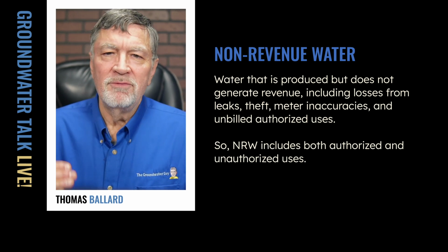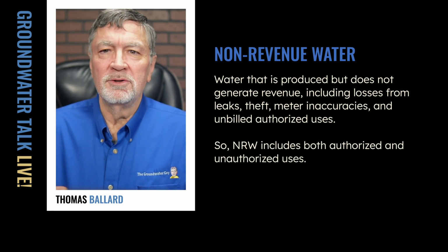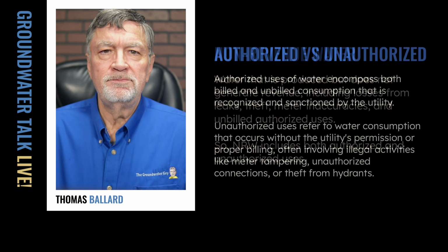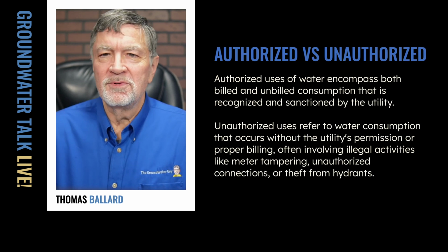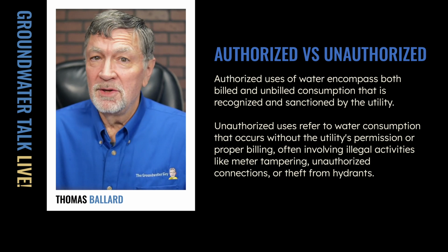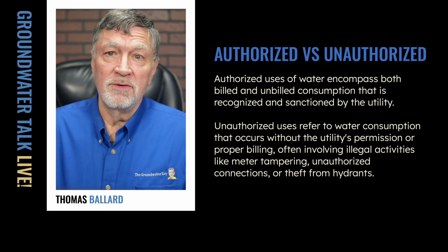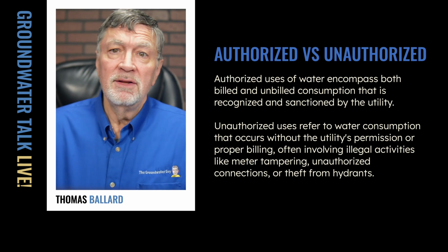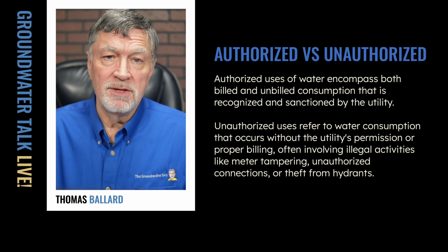So non-revenue water, or NRW for short, includes both authorized and unauthorized uses. All right, authorized versus unauthorized. This is an important distinction because authorized users of water encompass both billed and unbilled consumption that's recognized and sanctioned by the utility.